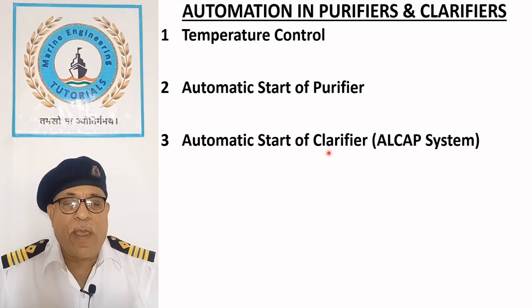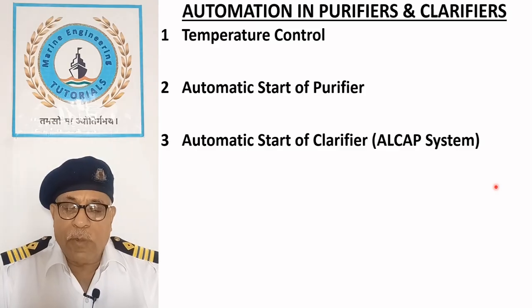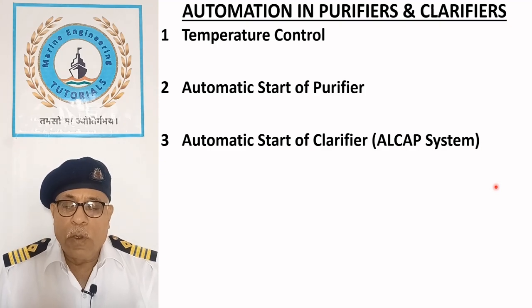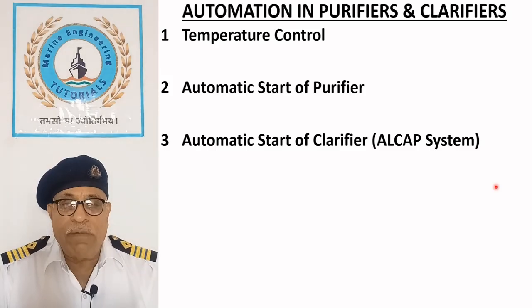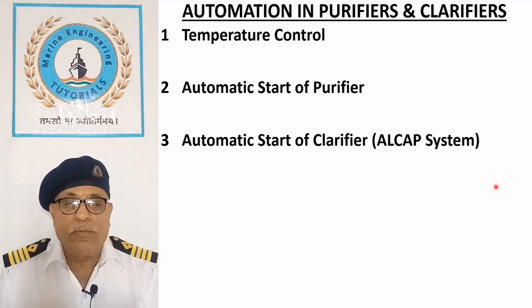Automatic start of clarifier in the LCAP system. When the controller is switched on, it supplies power to the solenoid valve to close the valve. It then starts the oil feed by operating the three-way valve and monitors the back pressure of the clean oil outlet.